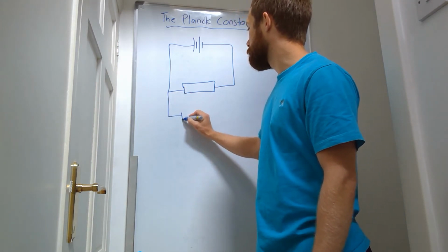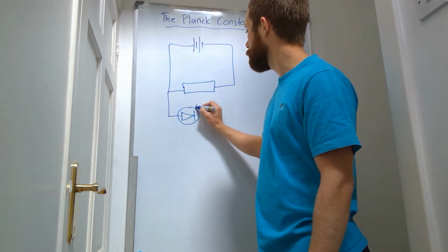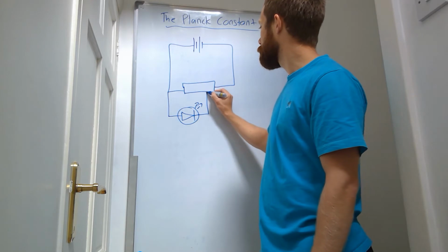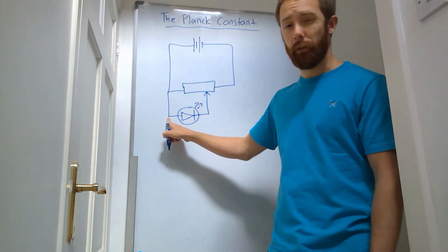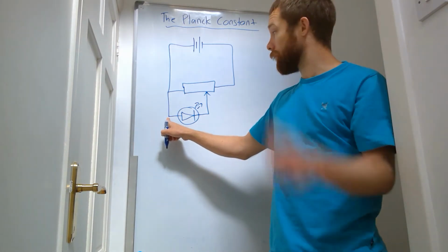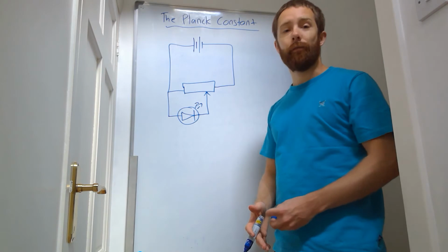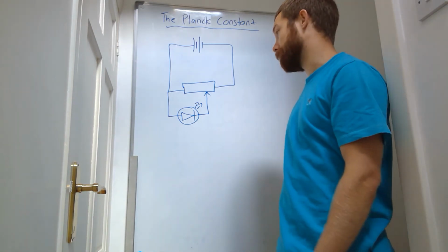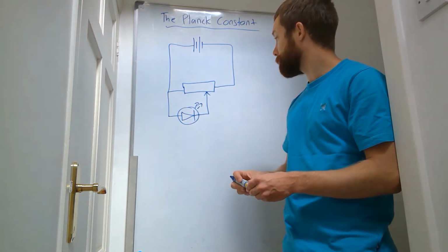This is then going to go through my LED here. I've drawn that so elongated, and that's going to come to our potentiometer. There's an option you could put a safety resistor in here. Most of the diagrams you see for this will have an extra resistor in here, but for the terms of the physics behind it, it's not really needed. It's just to protect your LED from breaking. If you make sure you've got low voltages, you're probably okay.